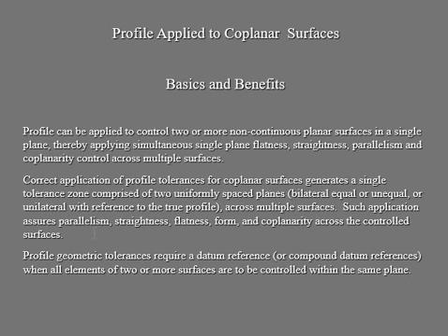So you do have the offset from the true sides. So anyway, profile geometry. Don't forget the common sense of what's going on outside, while we are so much into study like this. You need to connect to the real thing outside. So profile geometry tolerances, you're going to require a datum reference. So that's what's going on.